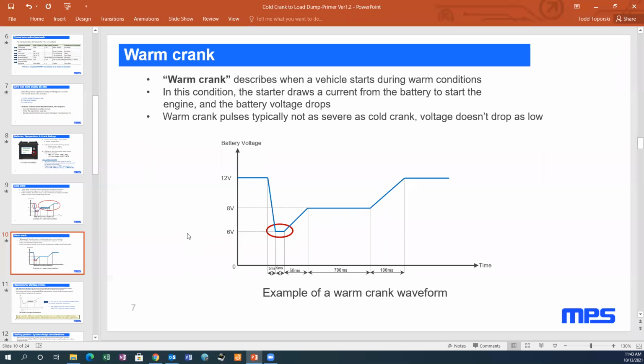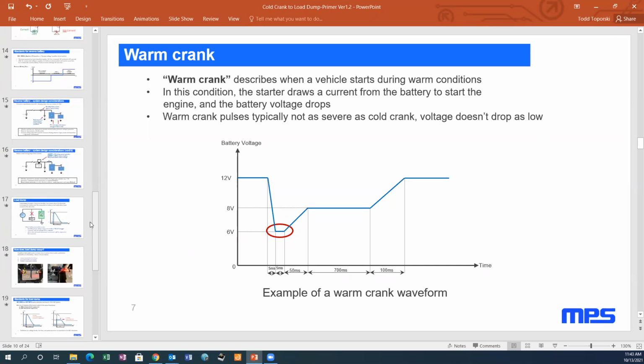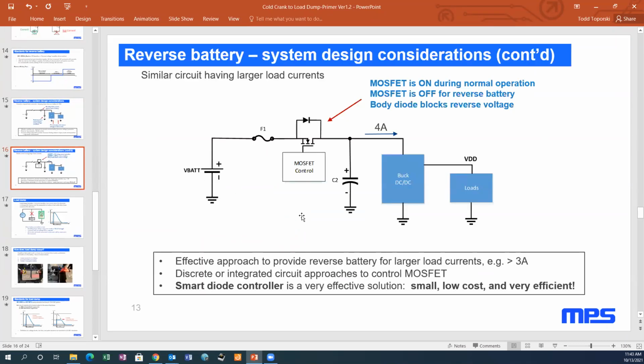Okay, next up, how quickly can your FET control switch off the FET to prevent the charge in the bulk cap from flowing back to the VBAT, as a diode can go to nanoseconds? How quick is the solution with the FET?